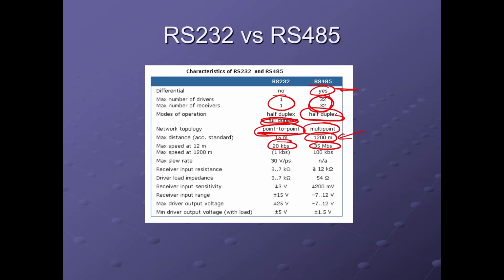We say, what are the 3 advantages of 485 over 232? So in a multiple choice question, you would get this, and you would look to find faster data rates or faster speeds. There's 1. 2 would be can be multi-dropped. So that's an advantage. It can be multi-dropped. And then 3 would be longer cable distance. So that's what we summarize as the 3 advantages of 485 over 232: faster data rates, can be multi-dropped, and has longer maximum cabling distances.